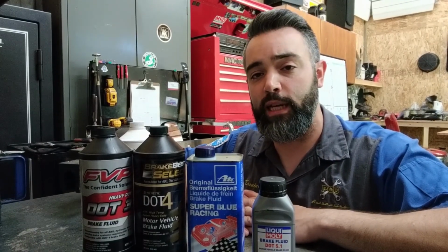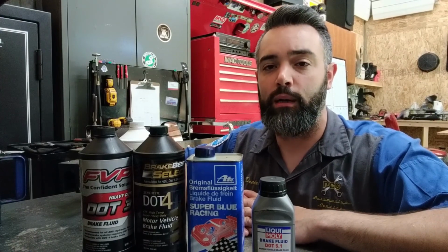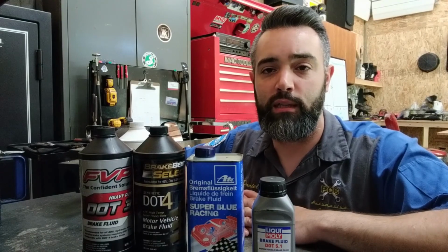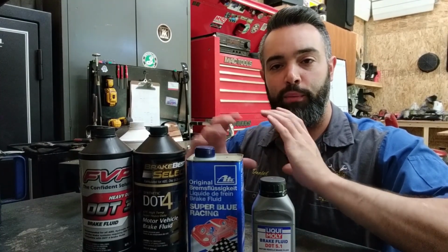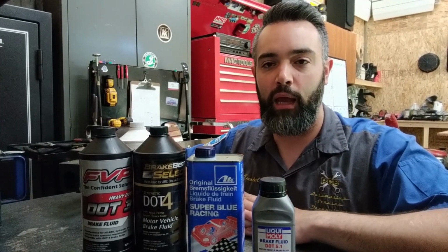If we have swelling of any seals, they can weaken, they can tear, they can rupture, and worst case scenario, they can cause seizure in the system. They can swell to the point where they don't let the two moving components move with respect to each other, essentially locking the system mechanically.